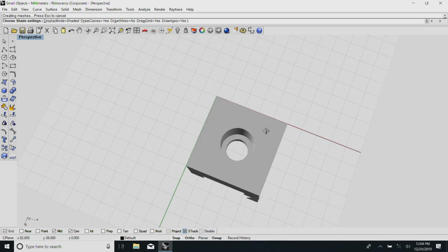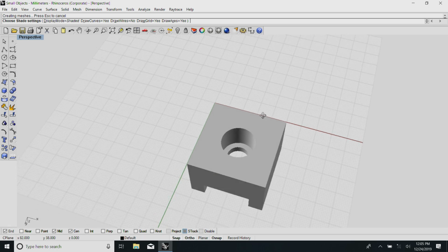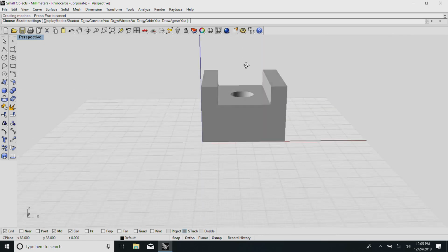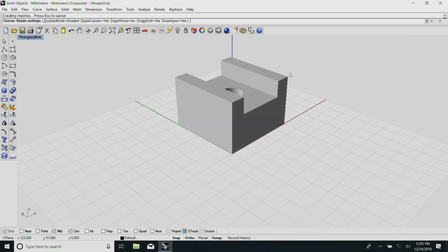When they try to drill a hole here, instead of using a milling cutter and trying to make the end mill do the job, it is very conventional for us to generally make a small pilot hole using a regular drill which has a twisted cutting edge. It is much faster and much easier. You see, the basic functional thing is now ready for us. But then that next little small thing,